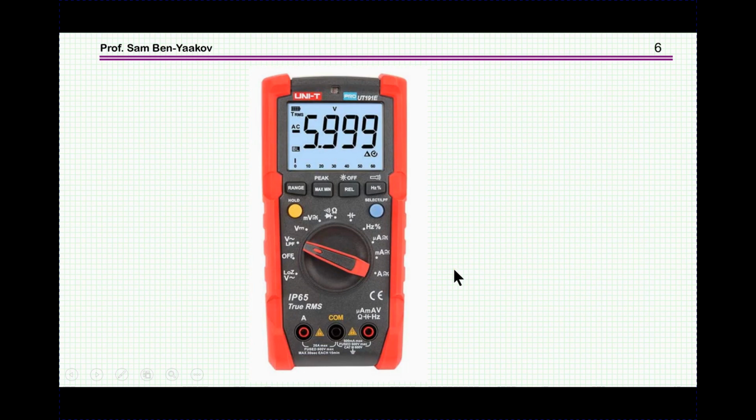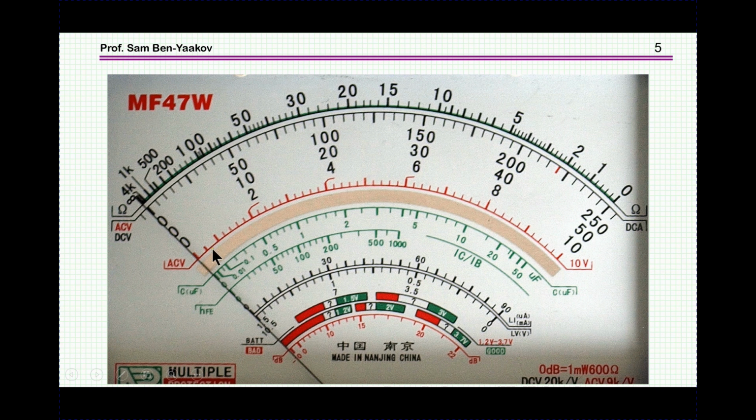Now today we are using digital multimeters. The display itself is linear. Most displays, and practically all of them, are fed by DC. So we do have to rectify the AC into the DC in a precision way. Let me just mention that this method is not very good because it's temperature dependent, and if you have to be very precise, then you have to match the temperature behavior with some correction. So it's going to be very tricky.